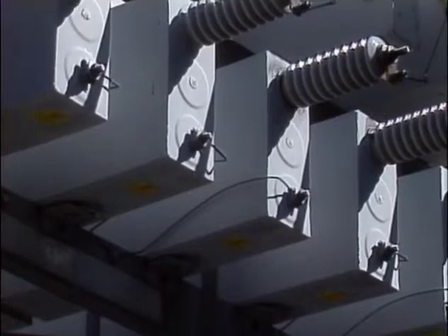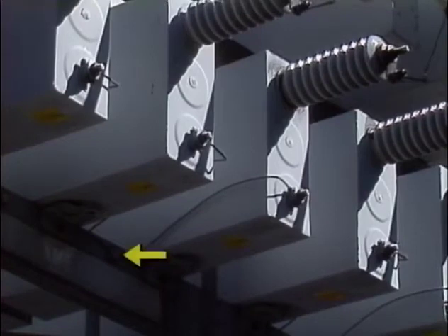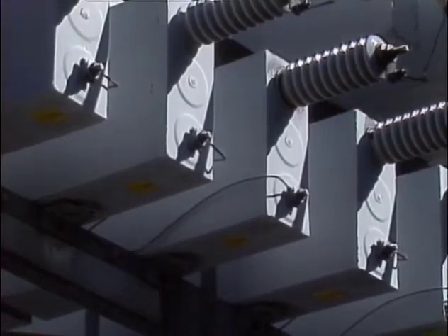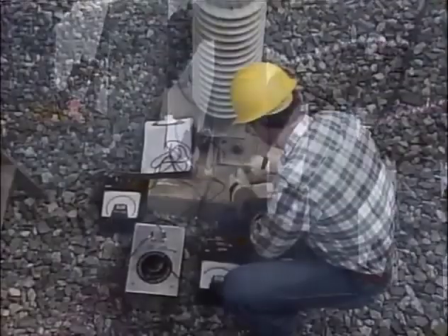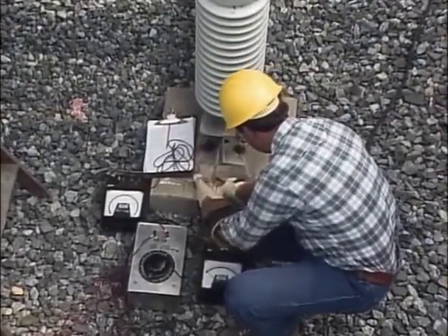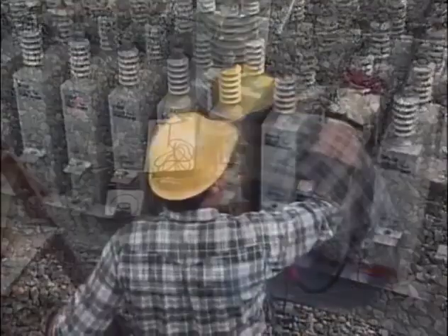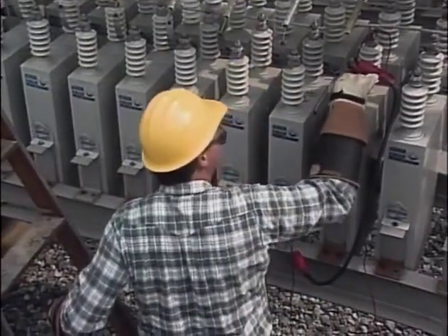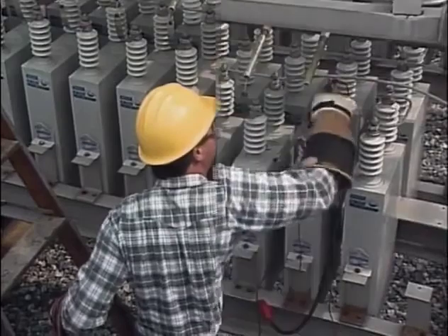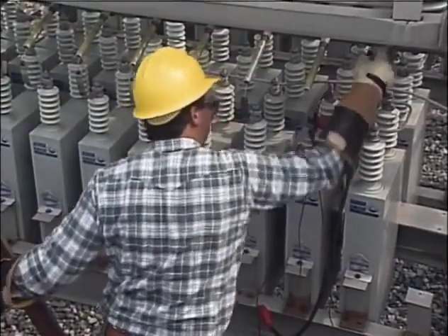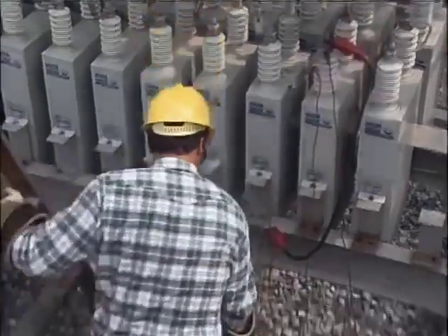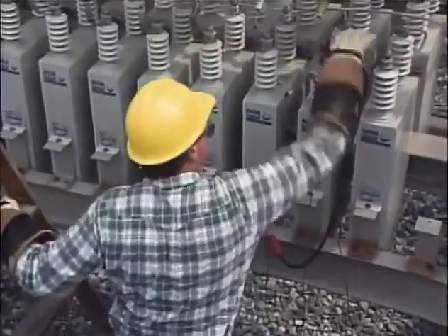The reason is that here, the neutral terminal is connected to the capacitor tank, and the tank is connected through the support structure to the other capacitors in the tier. Both the voltage supply and the voltmeter are also connected first to a suitable ground, and then to the normally hot terminal of the capacitor. After the instruments are connected, the short is removed from the capacitor and the temporary ground is taken off.